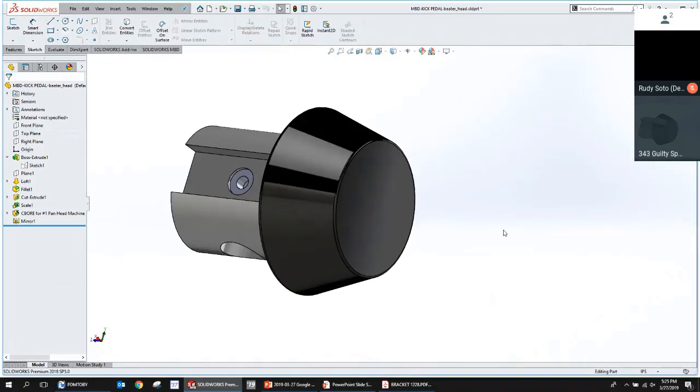Yeah, so it kind of comes back to the age-old SolidWorks design best practices versus machining manufacturing best practices. You know, where's the 000 on the model when you're designing versus where's the 000 when you're machining. So it can be redundant, but a lot of times it's not, because a lot of times you design something different than how you manufacture it.